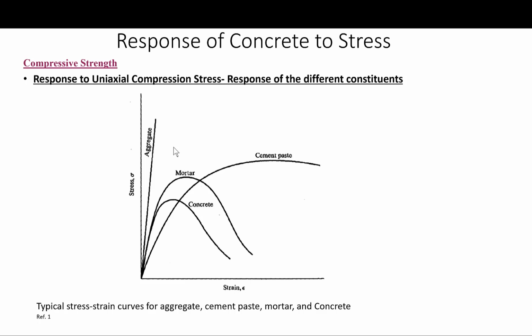These microcracks form at the paste aggregate boundary and through the mortar constituent of the concrete as compressive strain increases. Internal cracks and flaws exist, as we said before, before loads are applied. Some of these are due to segregation and bleeding, in particular beneath large pieces of aggregates or reinforcing steel.